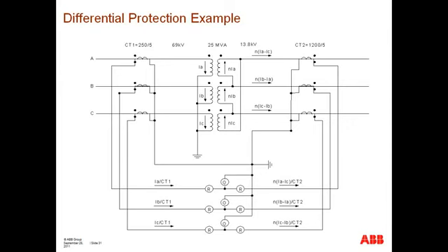In the case of modern microprocessor relays, most of the ones available from the major manufacturers just ask for voltage ratings and power ratings, and the transformer protection relay itself is able to determine what the ampere-turns balance should be based on the currents that are injected into it.